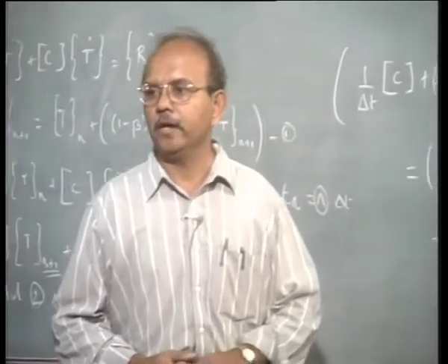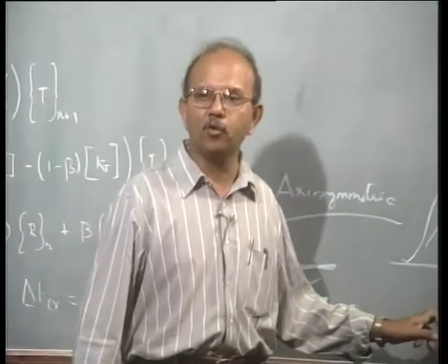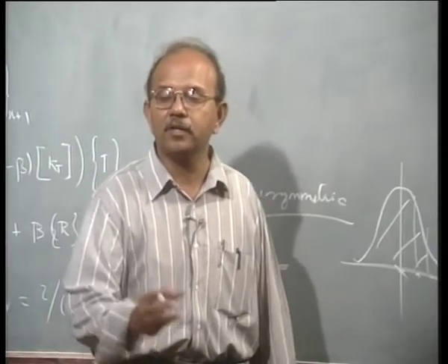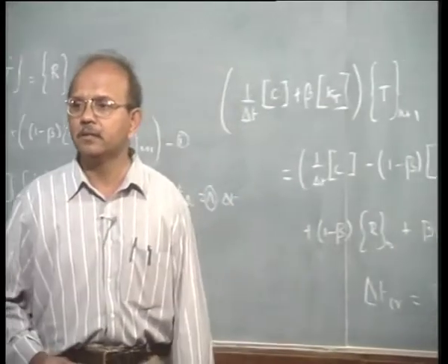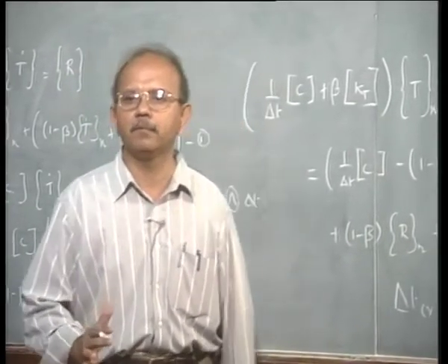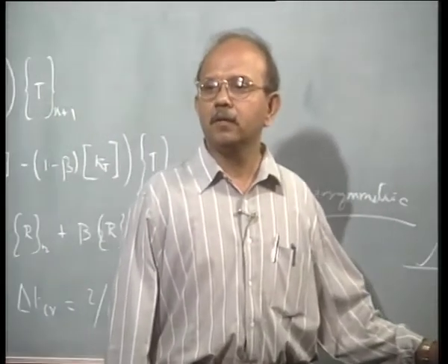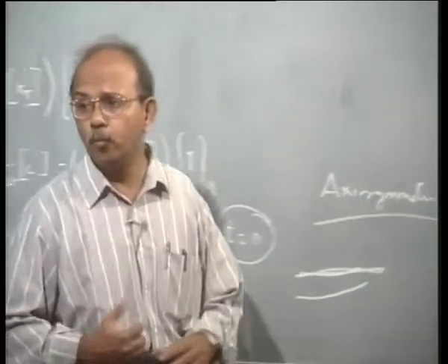If you are not so concerned about it, of course you can put all of it at only one node at the center. If you are not concerned about heat distribution very near the weld pool, then it is possible to concentrate the whole of it at only one node. But in this case we are actually not modeling the weld pool. There are a lot of other issues in weld pool modeling.